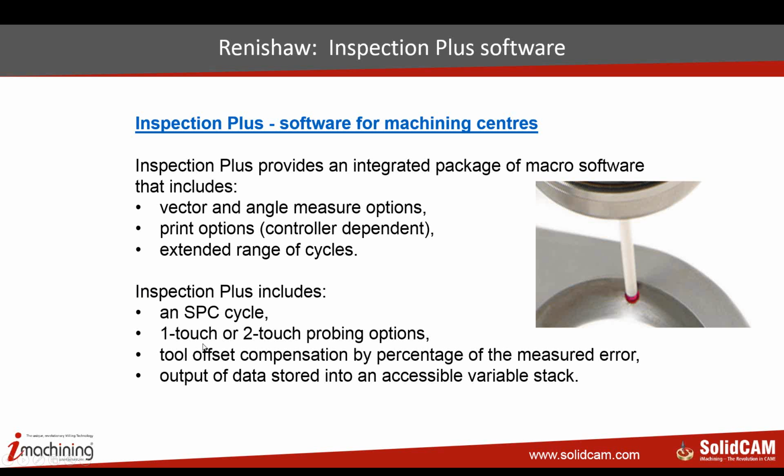For one example, Renishaw has now developed faster measurement cycles with one touch point, because in most of them you will see that the probe will go to the part and touch twice to get a precise location, a better measurement value. But they developed a one-touch movement measurement cycle with the same precision. So those are advanced options, advanced packages.